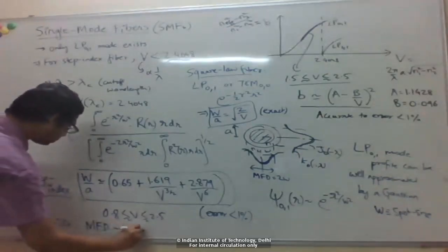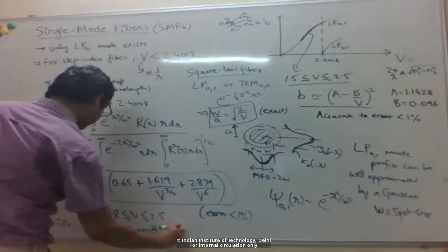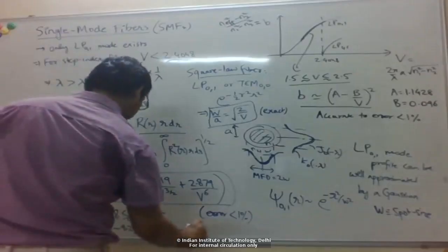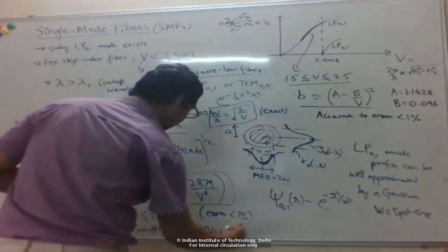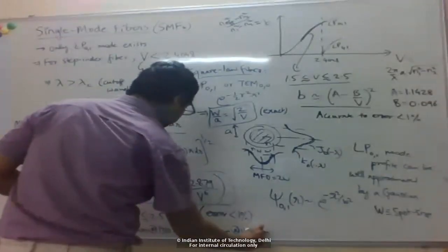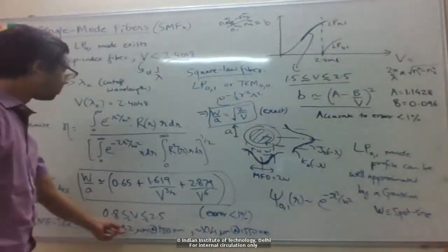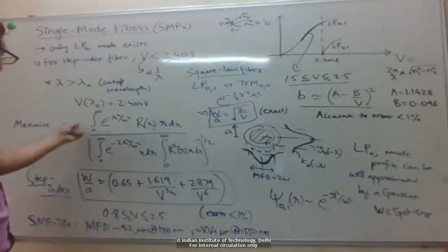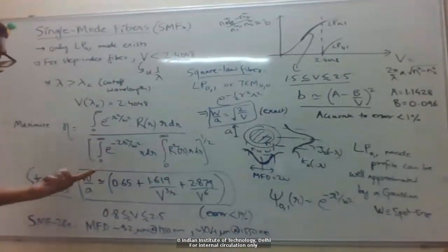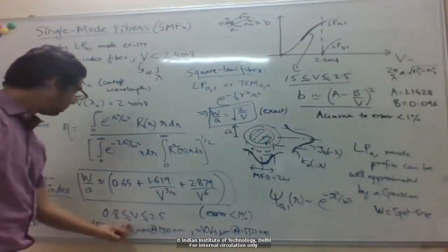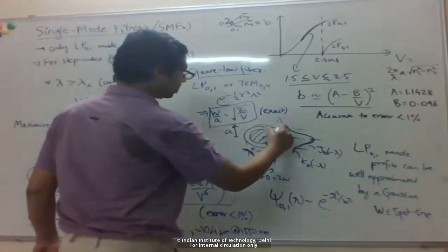is about 9 micron at 1310 nanometer and about 10 micron at 1550. These wavelengths are important for optical communication systems. So remember the core size, I just erased it, the diameter of the core for this SMF28 is 8 microns. So you can see the mode field diameter is slightly bigger than the core, 9 micron, 10 micron, because the field extends into the clad.